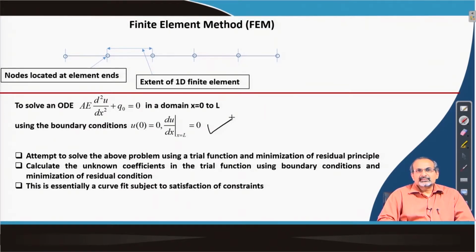You will realize at the end of an example that this is essentially a curve fitting exercise, and this curve fitting is done based on satisfaction of these above constraints that we talked about. That is, on one hand the boundary conditions, because it is a boundary value problem, and on the other you try to minimize the residuals all over the domain as you work out these coefficients.